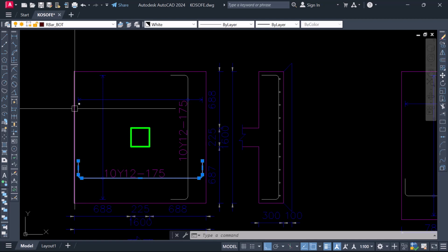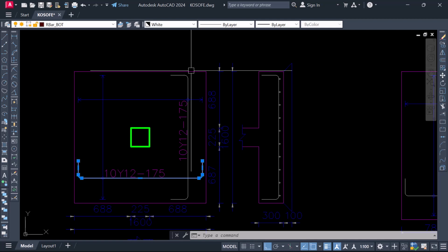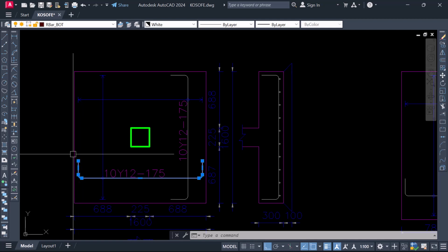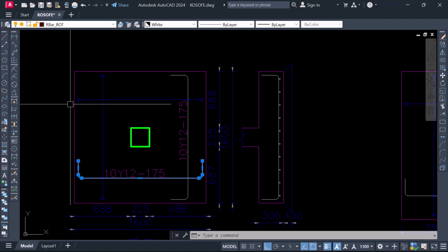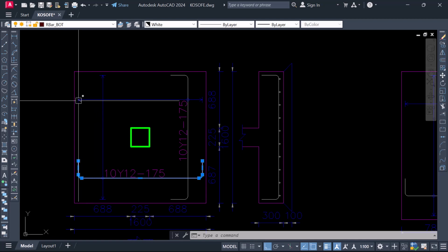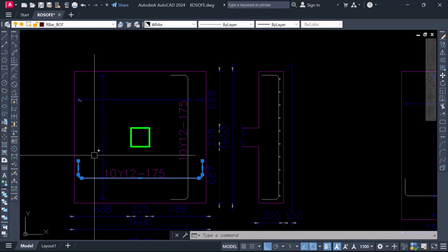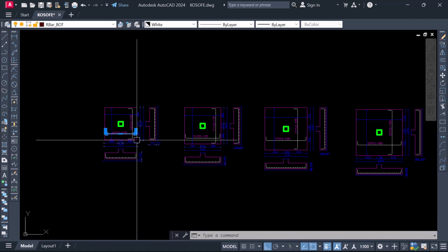You don't put it from the formwork, because this is telling you that this is where the formwork is going to start, at the trench. Right. So you don't put it from trench to trench. You're going to give a kind of formwork down to that 40. You can see 40 millimeter, because it's on the foundation level, you're going to give a 40 millimeter concrete cover. All right, so it's spanning over this length. So that's what you're going to do.